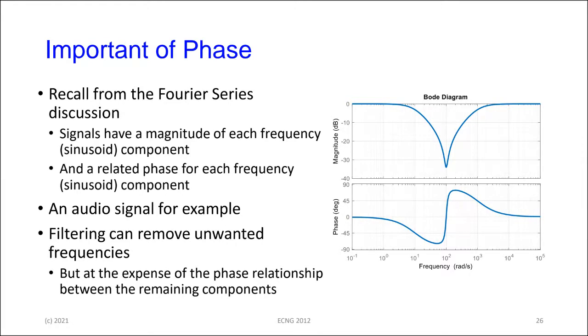So once you filter, you adjust the frequency components, and you may or may not drastically change what is passing through. Your intention was good, which was to filter, to remove something unwanted. But the result is that in removing something unwanted, you create something else, which is a distortion in the phase.